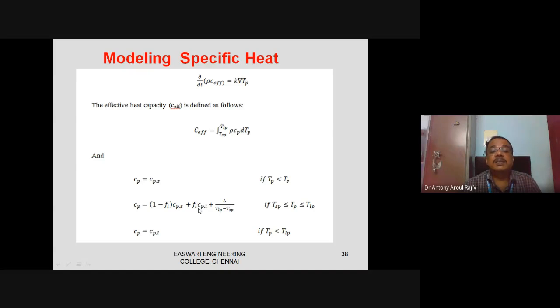So I am accounting for the specific heat as well as the change in the CP value, the physical CP value. See, here the CP is not the physical one. We are calling it apparent specific heat. The specific heat is not really increasing, but we are taking it as if the specific heat is increasing, so we are getting the solution. So we are happy. But really speaking, the PCM will be in a two-phase region, and I have to take the properties in the two-phase region.